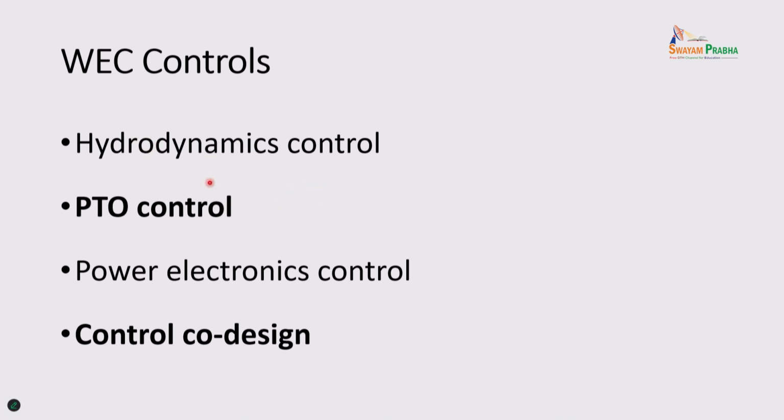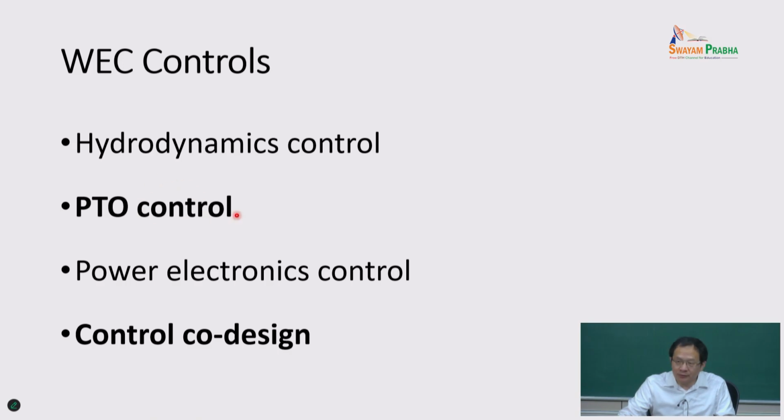You change the shape, right? I also mentioned the PTO control, right? Where you can control the velocity, control the force in real time. Okay, so what does it mean to control force? You have a generator, you control the force. In the mechanical domain, you put in the force sensor. And in the electrical domain, what will you do? You have a motor control force. Keep in mind it generates a force proportional to the current, right? Controlling force can also mean you control the current going through the generator.